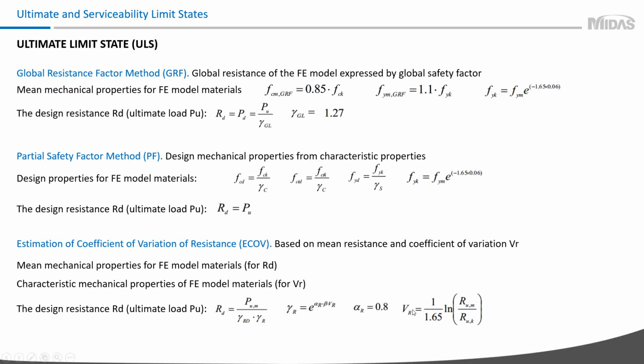And using this and results from the first file, you can calculate design resistance. It's up to you to select the appropriate method, but if you are not sure, you can perform these 3 methods and select the lowest design value. But the second gives quite conservative results.